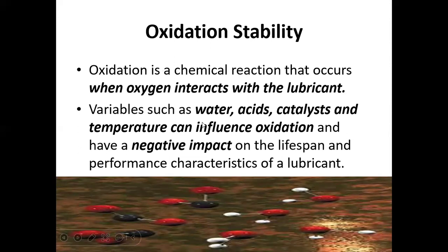So these are all causing corrosion or deterioration in our system because they introduce free radicals that could degrade the quality of our oil. And we don't like it because it will shorten the lifespan of our lubricant in operation. It's a waste of money actually, and there will be a tendency of damage in our system.